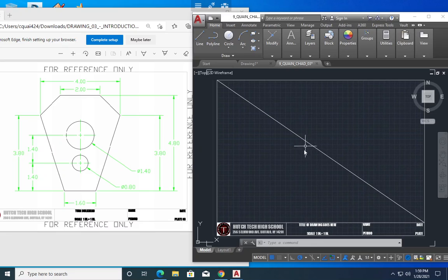So now you're going to ask, Mr. Q, how in the world do I find the center now that we've drawn this diagonal line? Does that really help us? And the answer is yes. If I was doing this on paper, I could draw another diagonal line going from there to there, and it would tell me my center point. But AutoCAD does something kind of cool for us. If I click on the object, notice what it does. It gives me the center point right here.